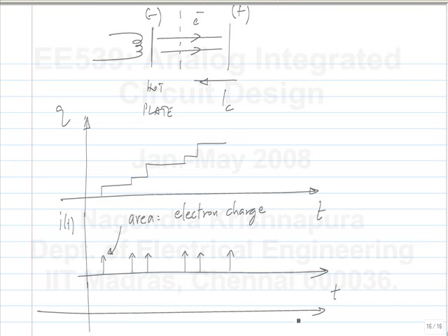So the meaning of noise here is, first of all, the I is not constant. It is a set of impulses, and the average value of I is some particular value, IC. The difference between the actual impulsive current that flows and the average value, that is the noise. And it turns out that the arrival times between these are in a Poisson distribution.